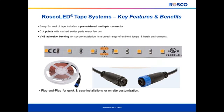It eliminates the need to do any cutting in the field, soldering, wiring of terminals. It can be very, very easy and straightforward. With that said, if you prefer to do some customization in the field, we do make it quite easy. You can see the cut points every few centimeters on our tape. It's clearly identified, as well as where those solder connections need to be made with respect to lead wire polarity, and in the case of RGBW tape, each one of those terminals is appropriately noted.